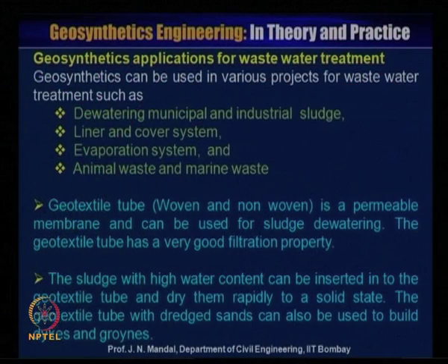So, geosynthetic application for wastewater treatment. Geosynthetics can be used in various projects for wastewater treatment, such as dewatering municipal and industrial sludge, liner and cover systems, evaporation systems, and animal waste and marine waste. Geotextile tube is made of woven and non-woven geotextile material,